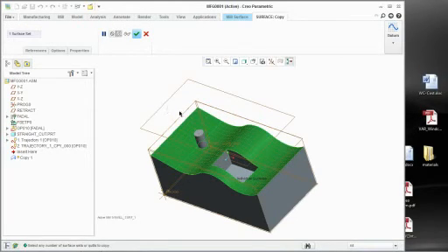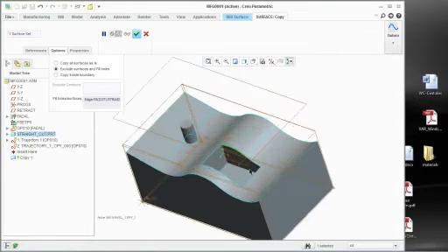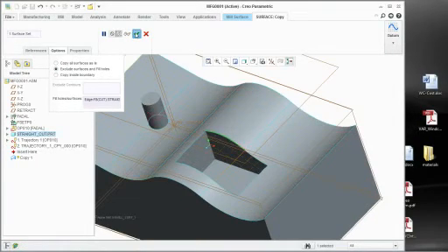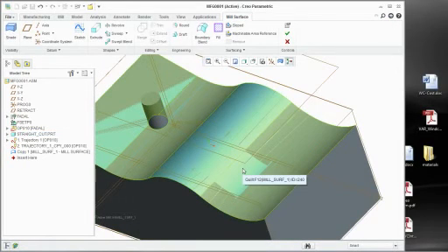If you want to patch holes like this, you can come into the Options tab and notice how it says Exclude Surfaces and Fill Holes. I can pick that, and say I want to fill holes, and I want to fill this hole, and notice how it fills that hole fairly easily. I think that was in previous versions of the software, but it's a way to handle the gaps you get when you copy and paste mill geometry.